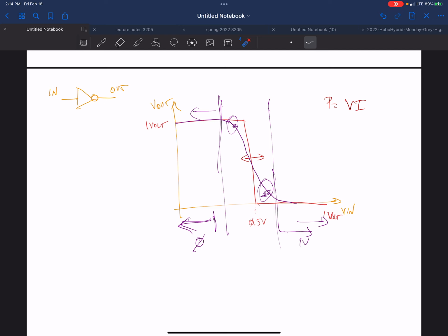You'd have a 3.3 volt supply and your high would be 2.4 volts or something, because you've got a bipolar transistor and there's a base-emitter voltage drop and so on. No good. So this is why reason number 2 that CMOS won is noise margin. And it's, again, the four quadrants: performance, power, cost, reliability. This is one aspect of reliability. You do not want zeros to get confused for ones and ones to get confused for zeros.